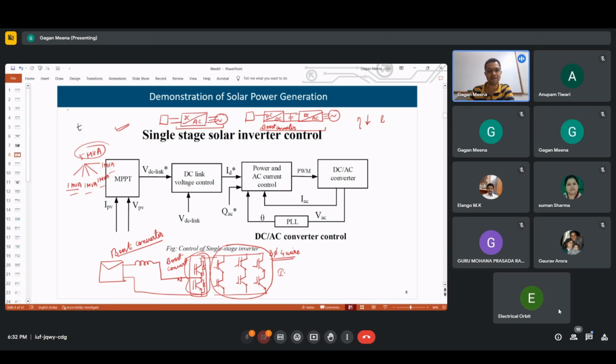So we are working with high voltages, so we need a power amplifier for that. If we remove the power amplifier, then it will become a software in loop. And here also, if storage is modeled using some simulator similar to RTDS, then it will become a software in loop. Let's say I model the storage in MATLAB, then it becomes a storage in software in loop.